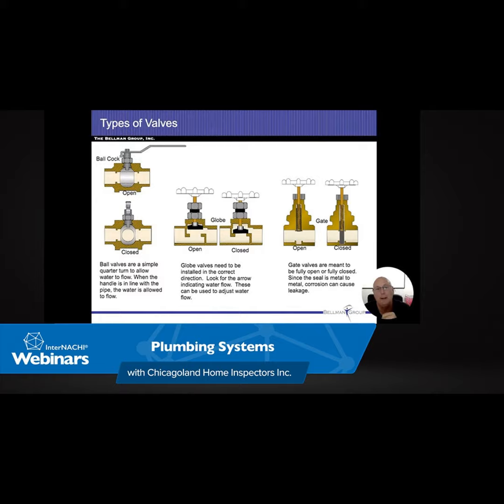Now, if I'm doing a home inspection and I see this, I cannot justify somebody making a change to it. But I might have a conversation that if it does need to happen and the plumber has to get into this one, there's nothing wrong with putting a 90-degree turn on it and bringing it towards us. At least that way it makes it accessible and usable. But I wouldn't do anything like that until the time comes that the plumber has to get in there.